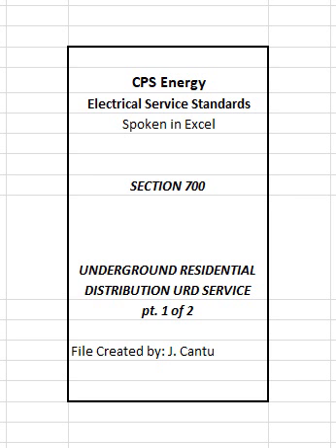704.1 Approved types of conduits. Standard service lateral conduits shall be Schedule 40 PVC with all elbows required to be Schedule 80 PVC. Where there is possibility of physical damage to service lateral conduits, Schedule 80 PVC shall be installed for the entire conduit system.